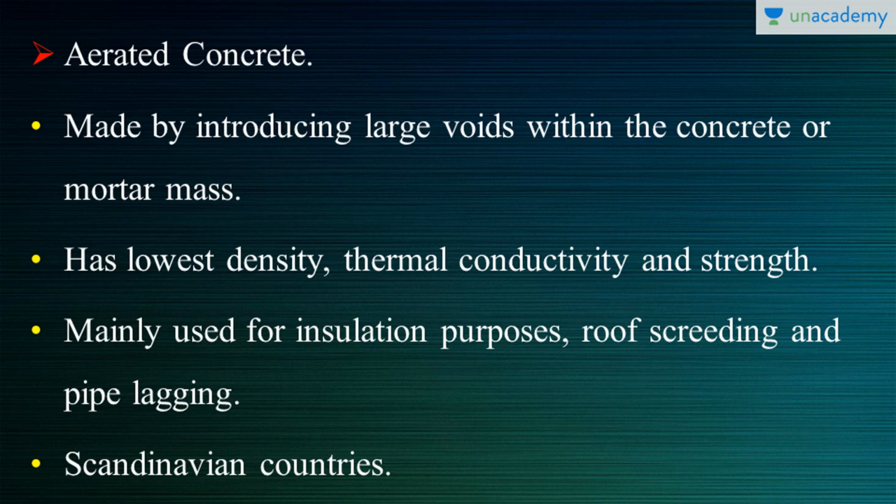So this is one of the points that we discussed during high strength concrete. High strength concrete is some kind of concrete that doesn't support the practice of aerating the concrete. So while we're working with an aerated concrete, we have to be very careful about the proportioning of the induced air.